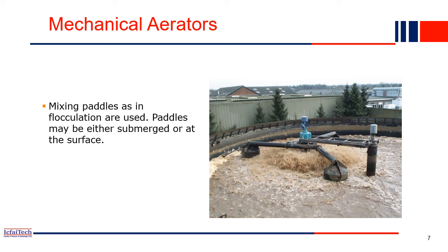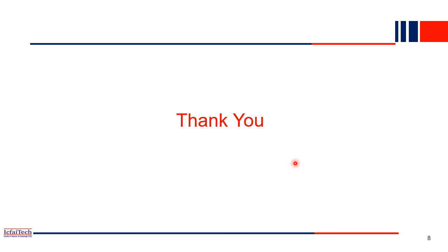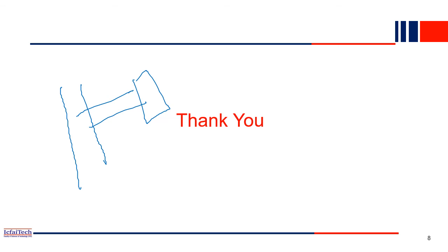So today we have discussed the aeration. Aeration is one of the very important parameters of a water treatment plant. Here we are releasing any dissolved gas present in the water, and oxygen will be added into the water. Now you can see in the flow charts, the first step is to collect the water from the source, and the first chamber the water goes to is the aeration tank. In the aeration tank, all the dissolved gases are removed, and we add oxygen into the water. Right, so this is the first step. After water stays here for half an hour or 1 hour, depending on our design, water will go to the next chamber for the next treatment. So thank you.